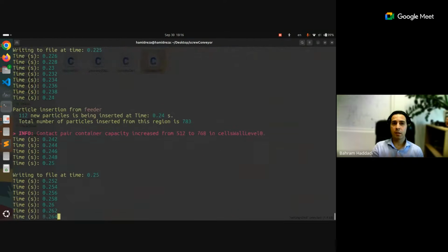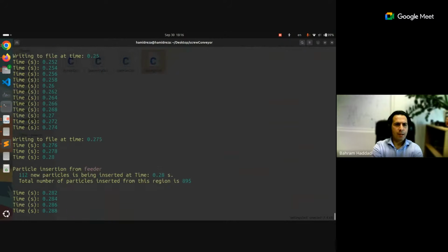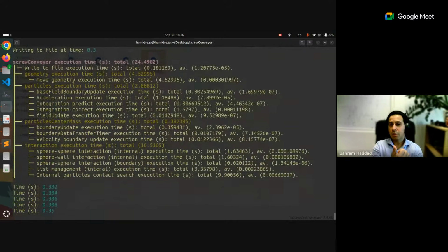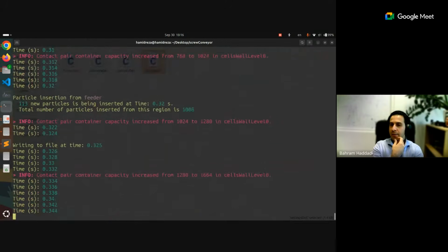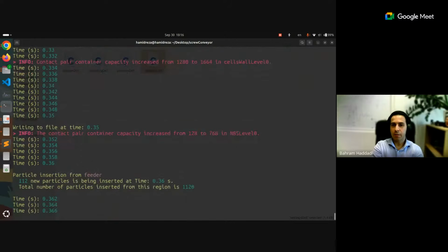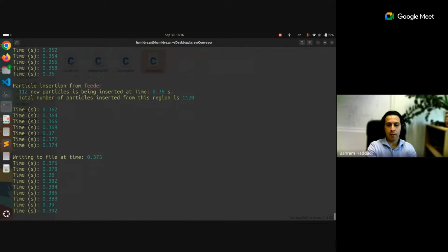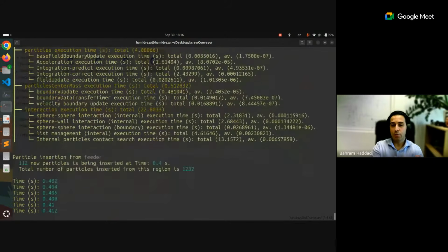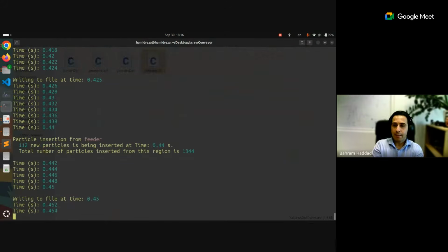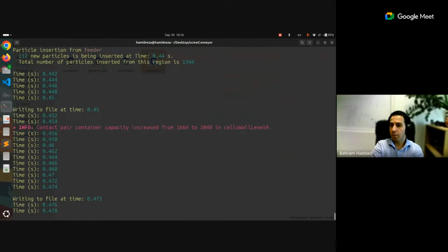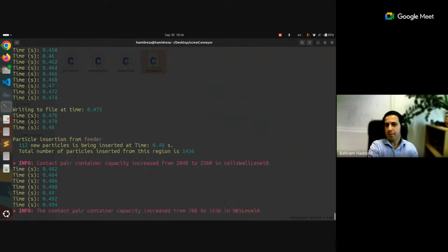You can also use tools like Salome. I also really like that. Salome does not just create the geometry, you can also do the meshes for the CFD simulations with it. And of course, there are many other CAD tools out there like SolidWorks, CATIA, so you can use any of them. As far as the tool that you're using can create STL for you, then you're good to go.